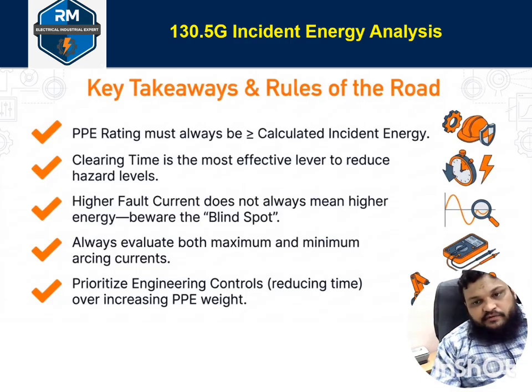The fourth one is to always evaluate between maximum and minimum arcing currents of the system. And always prioritize engineering control, reducing time over increasing PPE weight. So always prioritize engineering control so that we can eliminate the source or the hazard rather than relying on PPE. So that's it